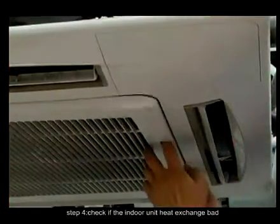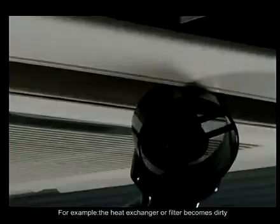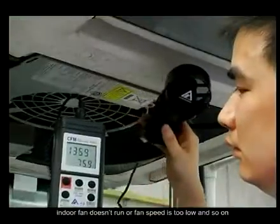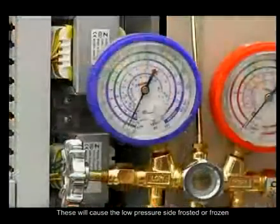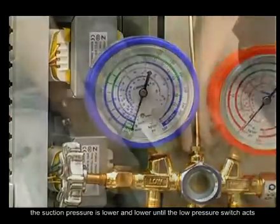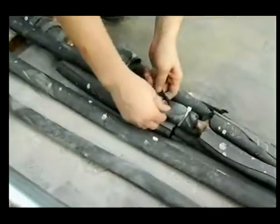Step 4. Check if the indoor unit heat exchange is bad. For example, the heat exchanger or filter becomes dirty, resistance of the air outlet is too big, the indoor fan doesn't run, or fan speed is too low, and so on. These will cause the low pressure side to be frosted or frozen. The suction pressure is lower and lower until the low pressure switch acts. If it exists, please check and exclude the malfunction.